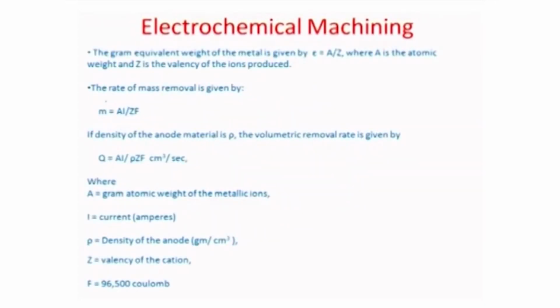So what we started doing is basically understanding how mass flow rate in terms of deposition or dissolution in an electrochemical process would happen, and it is given by Faraday's law. Faraday's law says that the total amount of mass removed is proportional to the current that is passed through the solution, the time for which it is passed, and something called epsilon, where epsilon is the electrochemical equivalent, or equivalent atomic weight, of a particular species, which means in turn that 1 mole of a species